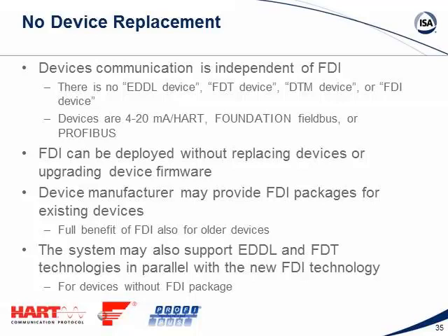And the same goes true for HART and PROFIBUS. It was built on technology that you can use for existing devices in your plants. It'll be some new files. There's going to be some new system software to be able to take advantage of this technology and all the benefits, but you're not having to replace existing devices. It's new features that are going to make it easier to interact with those devices in your system.